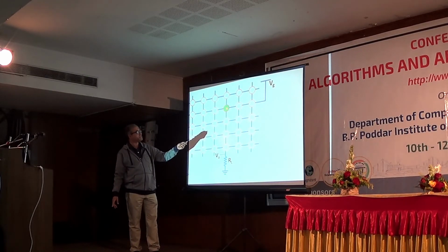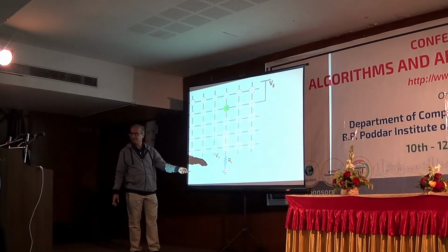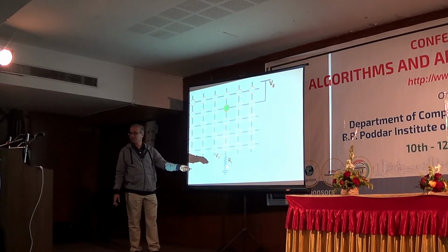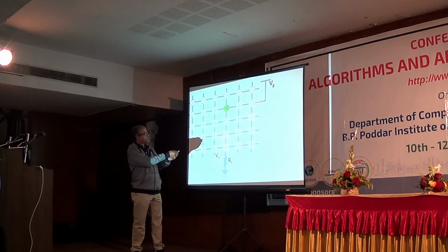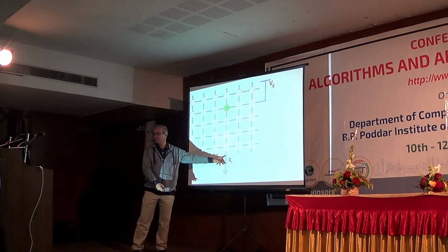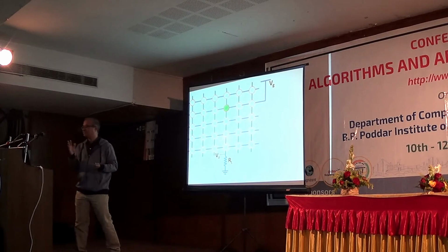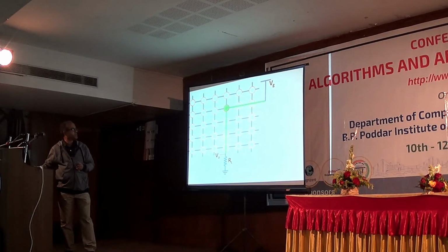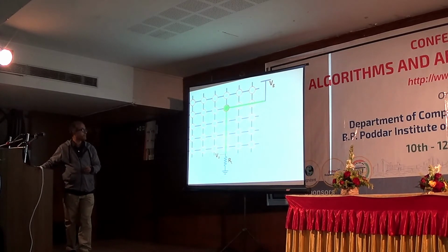If this memristor was conducting, on, then a relatively high current will be flowing. But if this memristor was off, very low current will be flowing. So I apply a voltage on the row and I measure the current flowing; there will be some current sensors here. This is one way in which I can sense whether the memristor is in the 0 or 1 state. This will be the current flowing path.